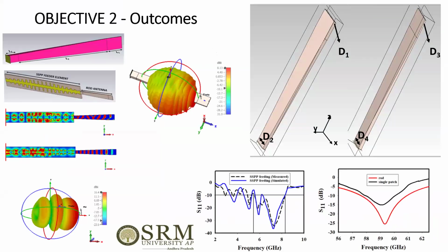So here I see several dips. What do they signify? Because I am getting around 7 gigahertz also, or 7.5 gigahertz, 6 gigahertz also I am getting. But here I have taken the major lower value, sir. Very low reflection coefficient value I pointed out here, sir, as 7.3 gigahertz. If I start simulating at the 5.9 gigahertz dip also, I'm getting lower gain, sir. I'm getting only at one point my gain increasing to 16.4 dBi, and that is 7.2 gigahertz.